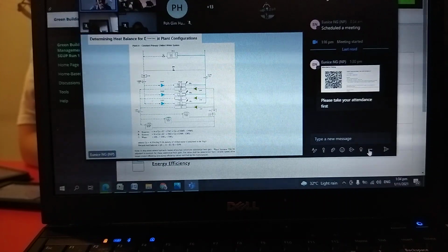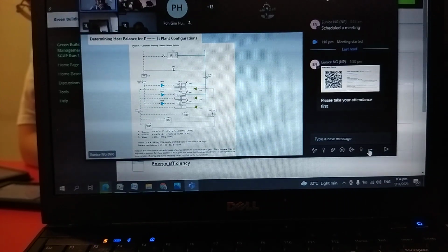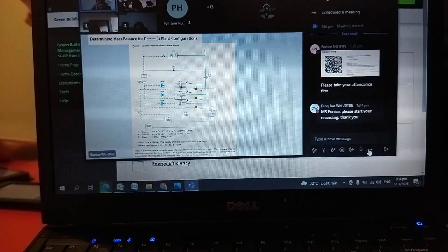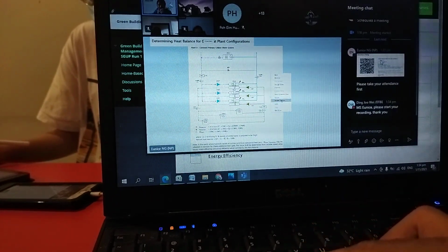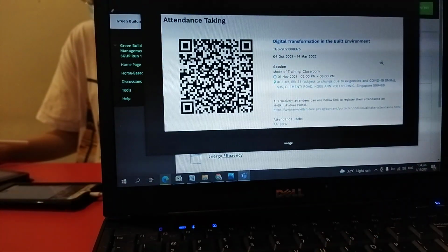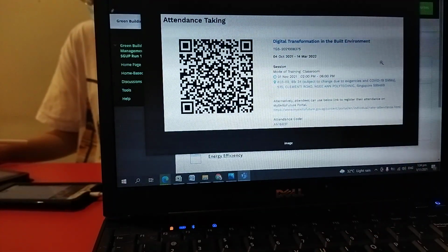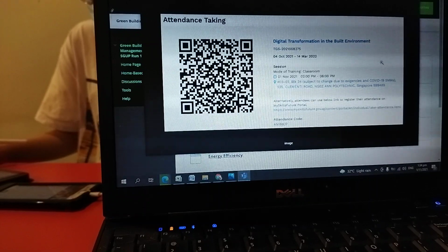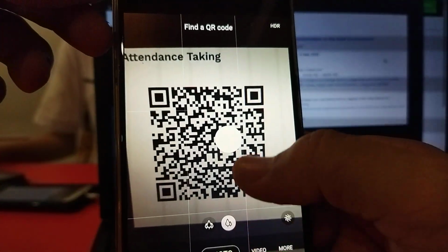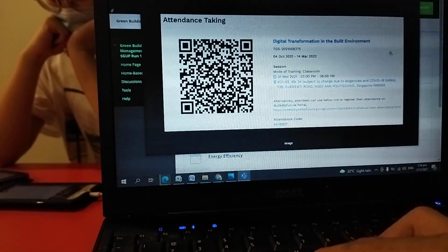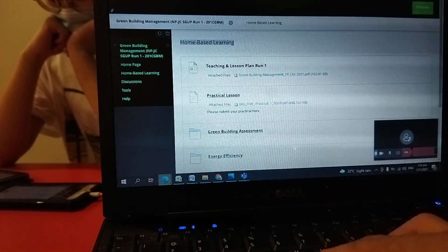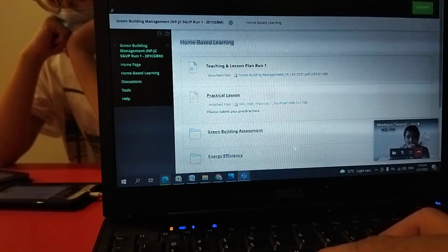In the primary constant system, you see that there's only one pump that sends water to the cooling coil on the AHU that I showed you last week in my lab. This pump is a constant flow because of the chill water flow through the chiller. In the old days the chiller didn't have that technology, so the chillers are on constant flow. You will see this type of arrangement in buildings, because the pump will flow at a constant speed, regardless of the flow.